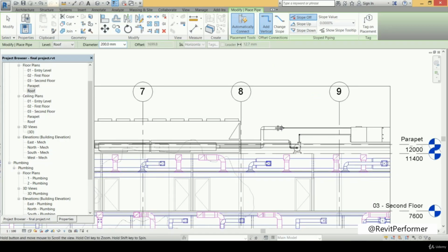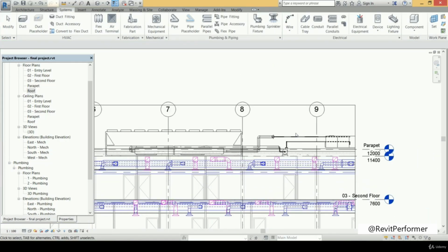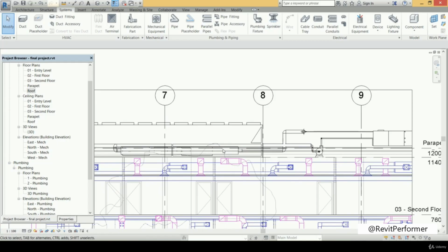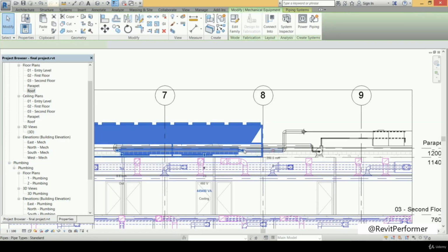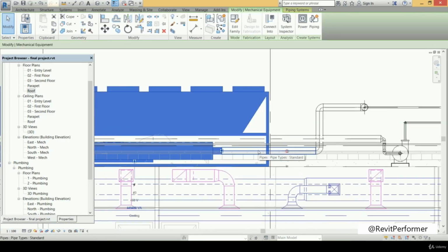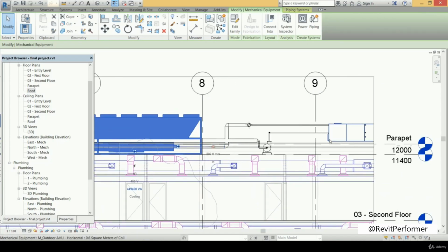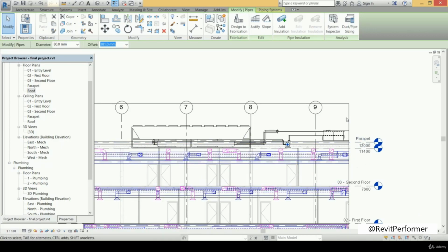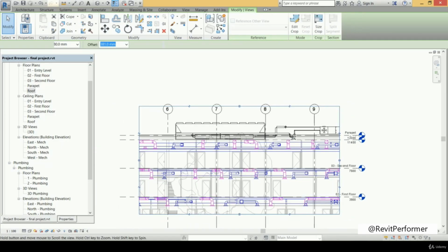Very good. Here, what we did exactly is to connect the output of the chiller directly to the input of the air handling unit, and we connected the input of the chiller or the input pipe as you see here. We connected it with the output of the air handling unit, but we connected it through that element which is a pump, as a pump will push the water from the chiller to the air handling unit. So to see the full picture, we can increase that section here.